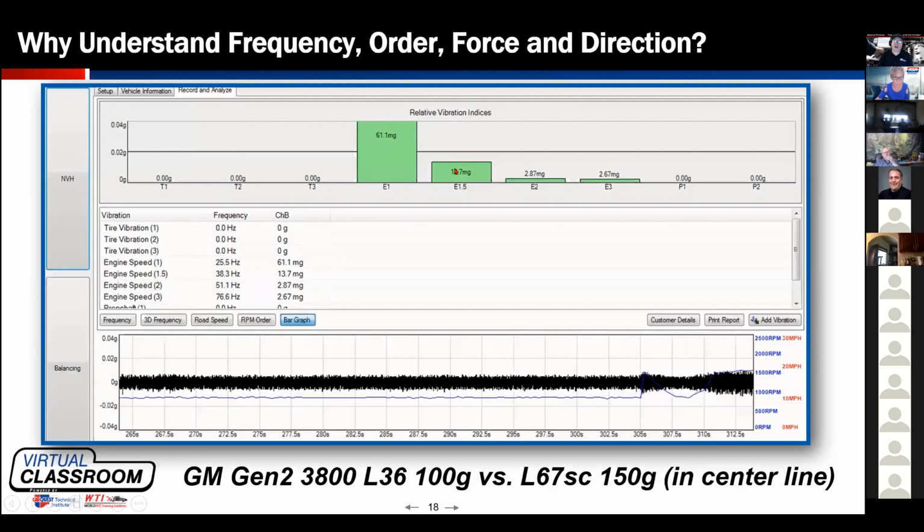There are a few vibrations over here, but what I'm feeling is what I refer to as an engine order 1 vibration with a massive amount of force. By just looking at this graph, I can tell you, guys, that can't be a balance shaft. No. If this were a balance shaft issue, and this is for another class further down the road, it would be showing a majority of the force under an order 3.